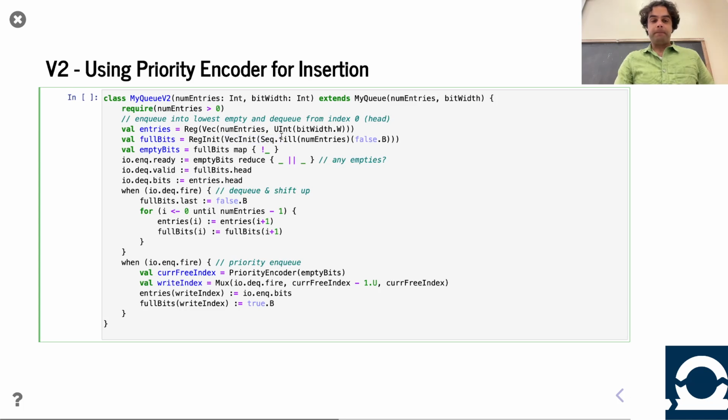Cool. And then we see some kind of interesting code. So for example, we have these registers indicating if it's one, that means the corresponding entry has legitimate data, i.e. it's full. So for writing the logic out, I thought, gee, wouldn't it be nice to be able to say something is empty? So it's just the negation of that, right? If something is not full, it's empty. So how can I do that? Well, I could take the full bits and just map them all to the not symbol. So once again, the functional programming is extremely concise, right? If you and your readers notice functional programming semantics, this is probably more clear and more concise than doing it the long way with a for loop or something. So this is a case where I think it's a good use.